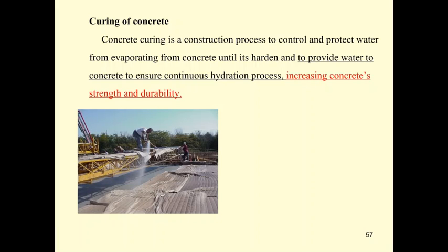After you mix the concrete properly, with the proper water, the proper aggregate, the proper cement paste, and the proper water cement ratio, you pour the concrete into the formwork and compact it with the vibrator. After you leave the concrete for about a day, it will start to harden. When concrete hardens, the cement uses the water, and the amount of water in the concrete reduces.